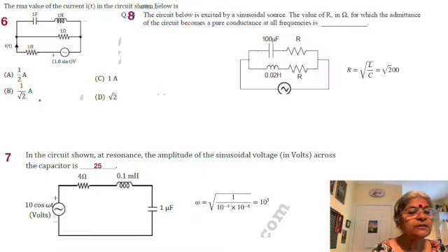Again, there is an AC source given as 1 sin t, so omega is equal to 1. And there is a resistor connected to it, and then we have two branches. One is the 1 farad, 1 Henry in series. So if you give omega to both of them, one will become j1, the other one will become minus j1. That is, the capacitor is minus j1, the inductor is j1. So it's a short. And so the 1 ohm connected in between is shorted.